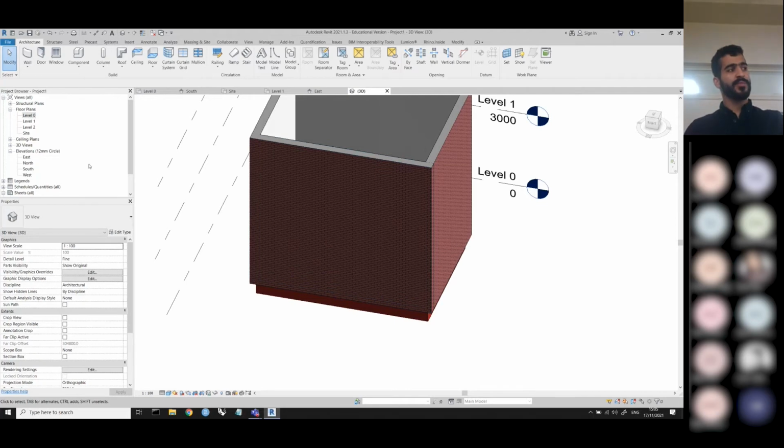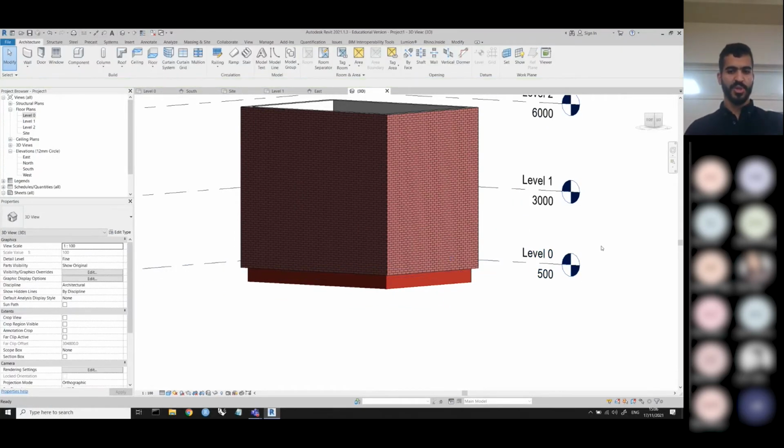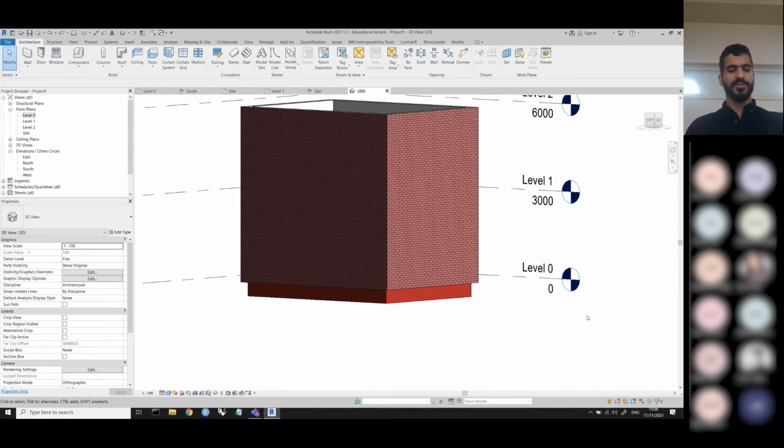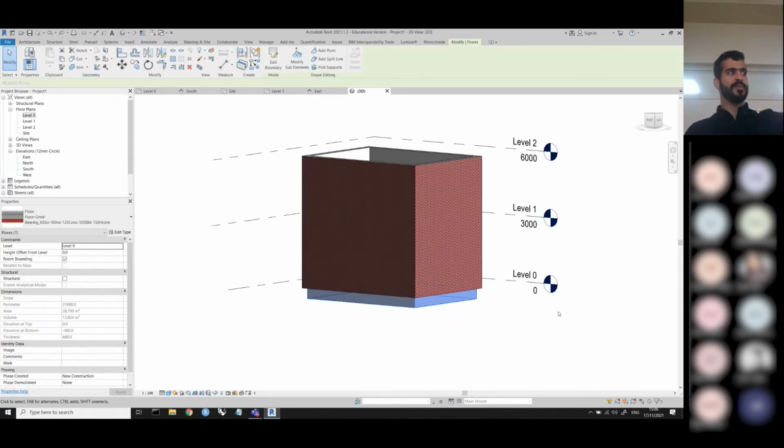Because we did it in ground 0, on level 0, it should be restricted to level 0. So here, if I change this, yeah, I'm going to Control Z because we want level 0 to start at 0, just because it's easier to work with for the tutorial. You can see the constraint is to the top of the floor, right?